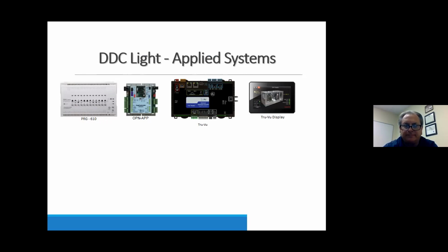We just did a fairly large facility for FedEx, where they needed a bunch of lead lag. They had to have cooling in specific areas if something went down. So we had to do a bunch of lead lag control on different types of equipment in the facility. There's a lot of applications that you run into. Again, you can throw a big DDC system at it, or you can make it a standalone application, single panel control with DDC controllers that have the number of IO that you need to do and the ability to do a light front end to see it.